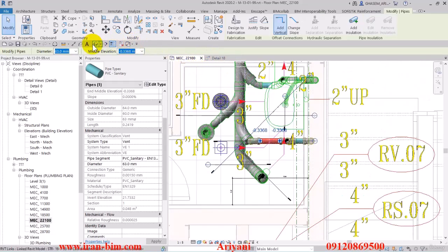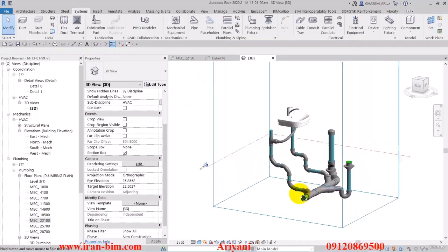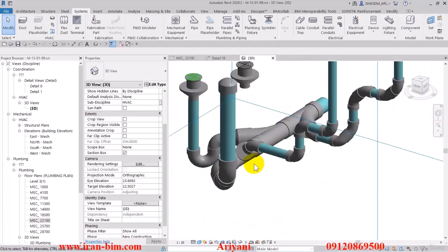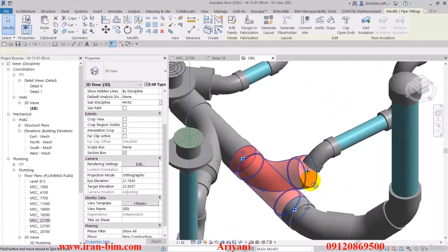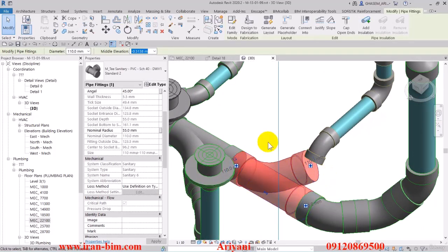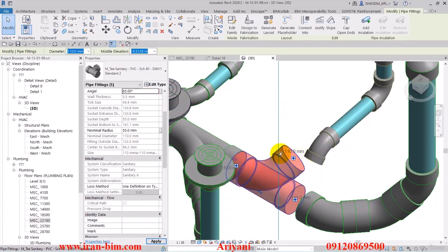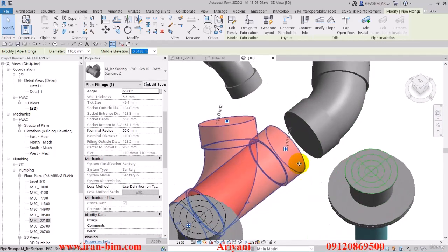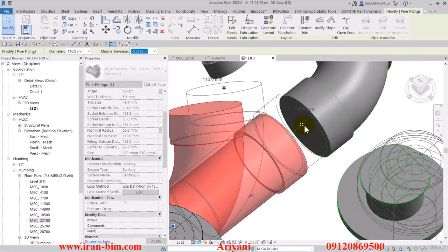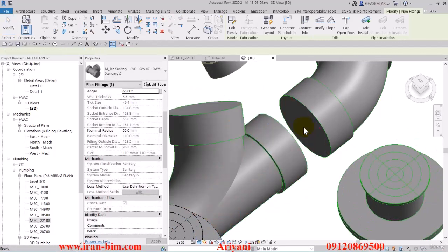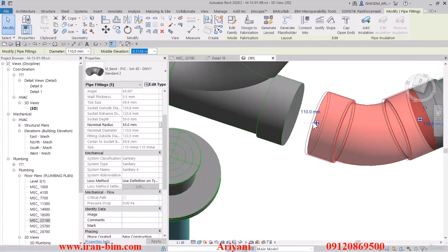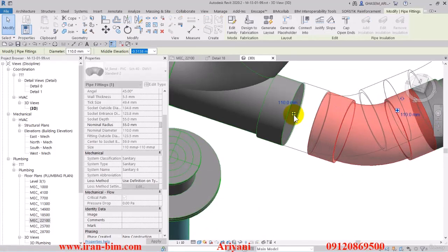So we'll go over to the 3D view to get a better look at this, and now we're actually modeling this part over here. Now in order to connect these two up, first I'll select this part and change its angle to 65. There we go. So now we can connect these two up. So we select the three-way fitting, and then we drag it over here, Control Z here, and then let's select the other piece instead and move it over here and connect it to this one.